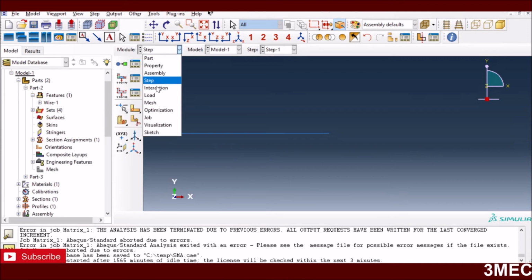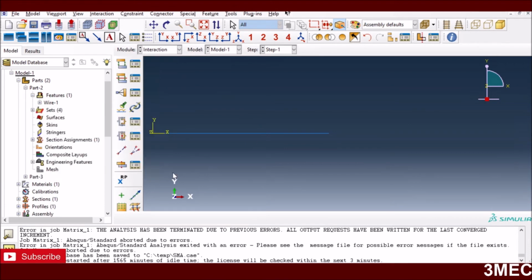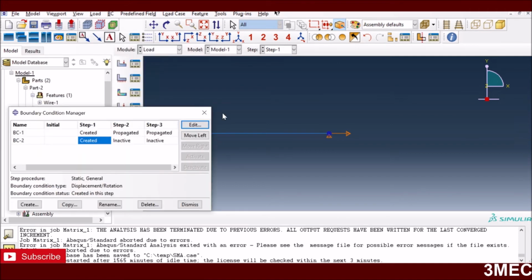Okay, so this was just based on that. Just consider you have 1 step, right, for the timing. There is no interaction because it's just 1 component here, which is a fiber. So I leave it like that. Then I go to the loadings, and loading is very much the same as they had in their experiments. So I have no forces, but it was a displacement control test.